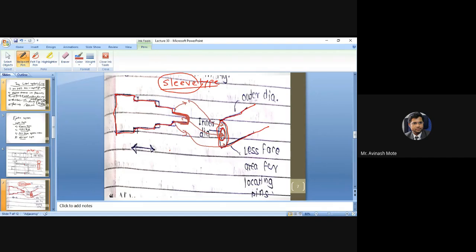So your question will be, why is there this uniform section rather than this step section? This is because you can use the same kind of sleeve for different products with different diameters. If the diameter is more, this cross section can be used. Again, for more diameter, this cross section can be used.